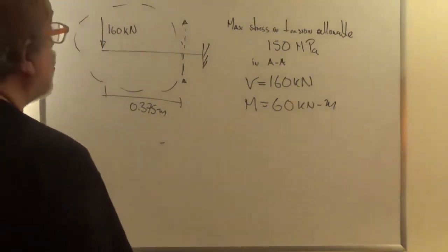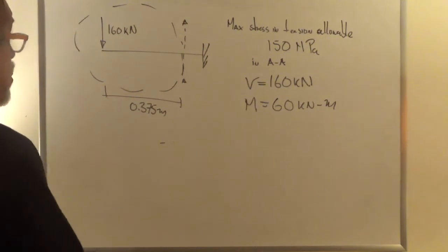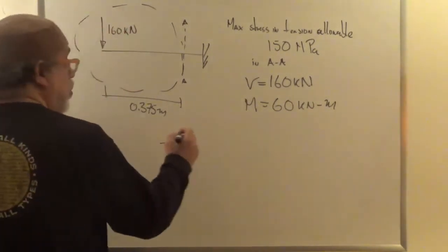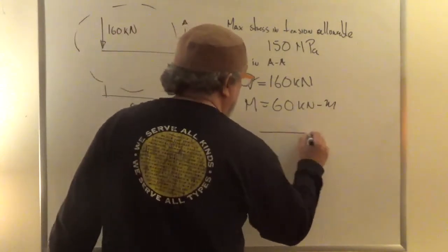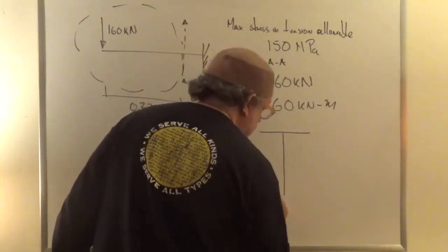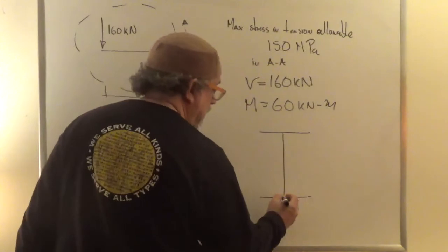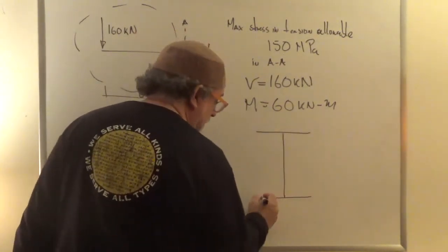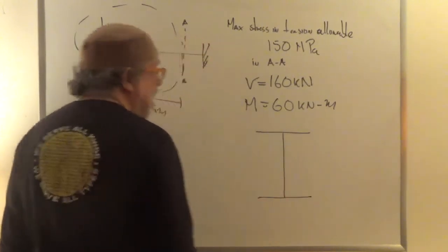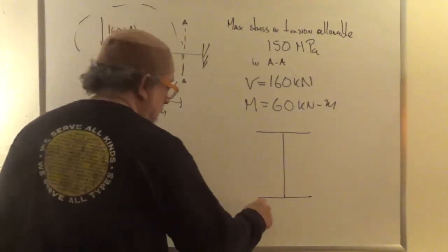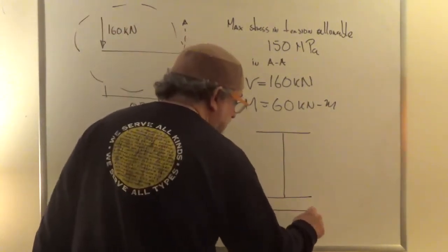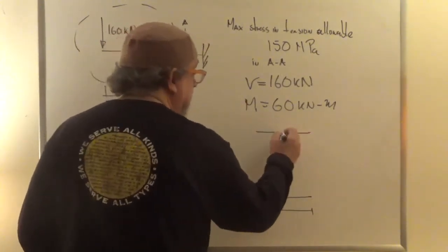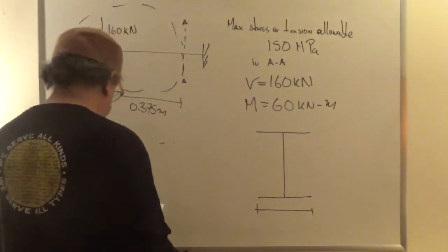Of course, in order to calculate stresses, I need to know what the cross-section looks like. So let's say the cross-section is an I-beam. To be really precise, I should draw the I-beam using the specific thickness and fillets and all of that. Well, let's use our often used idealized approximation in which we just represent the plates as lines at their centers.